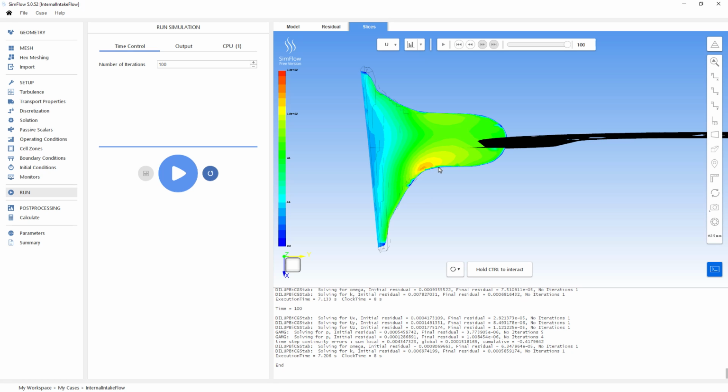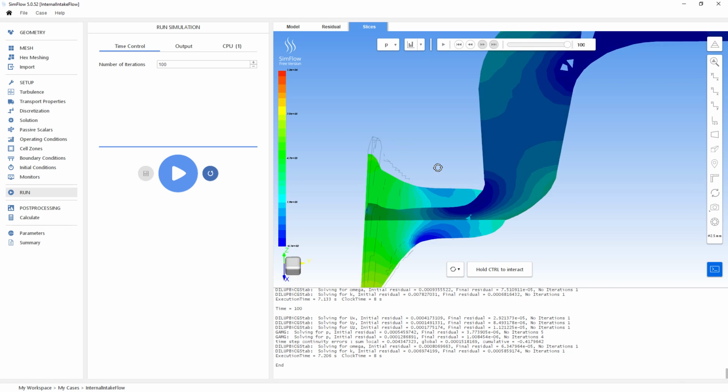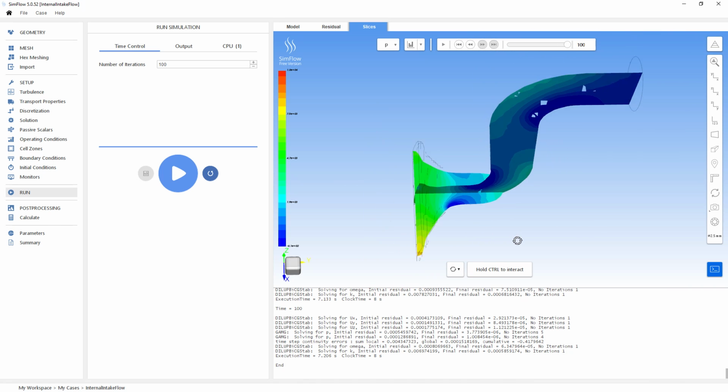So what this would tell me, as I'm designing this, in both the pressure and in the velocity, is it would be much better if I could get this to transition quicker, or maybe make this front plate flat and then have the duct start over here. That way I wouldn't have this issue here. Now, remember when these were designed, it's because there is some sheet metal that's kind of in the way, and that's where the mounting points are. So there's only so much that you can do, but if you're trying to optimize a design like this, those are the things that I would look at.